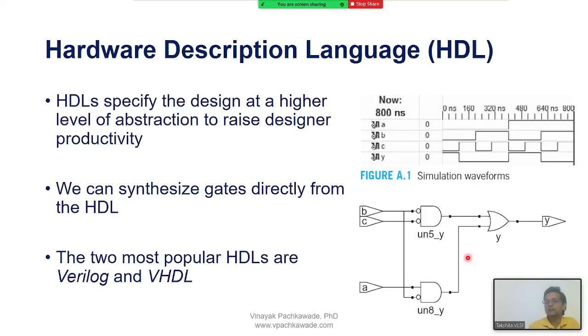Then there is a tool called a logic compiler, right? When you write a code, that code can be verified by that compiler tool, and you will see a set of waveforms like over here, and the logic design team will verify this design. For example, what are the inputs, what are the outputs. If there is a clock also, they will see the waveform for the clock and accordingly check whether the gates and the logic are performing or not. That is the job of the logic design team and the HDL, hardware description language.